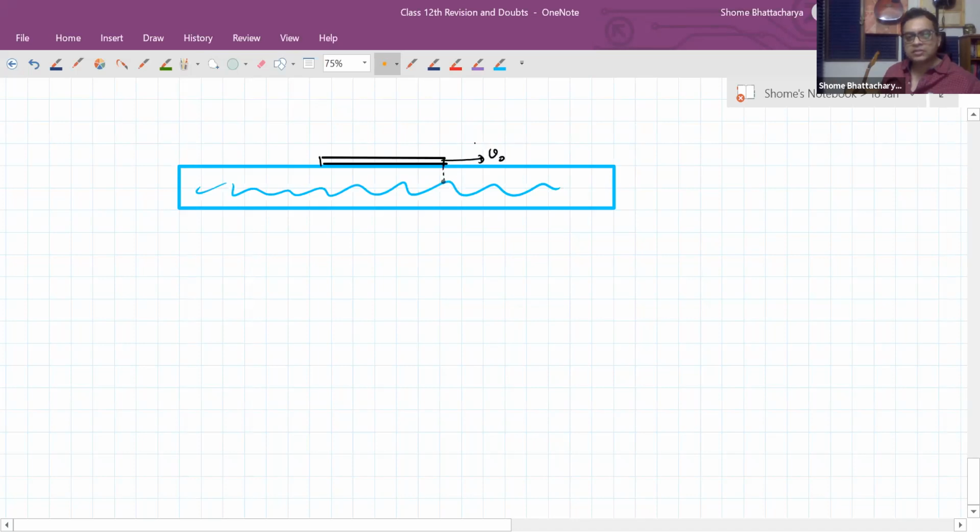Whereas this will be the assumption that because the surface below is rough, the velocity of that point will be tending to zero. So that laminar flow will have a velocity gradient which looks like this. If this is your y-axis, your delta v by delta y will be more or less equal to minus v naught by h, where h was this height.